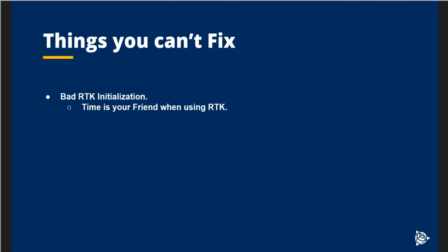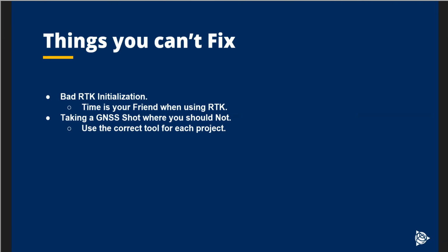It's good practice. If you haven't had your initialization and moved 50 feet, or you haven't had it for 15 minutes, it may be questionable. You've got to be careful. The receivers are getting better and better, but it's up to the person in the field to know that that's good. You can't fix that in the office.